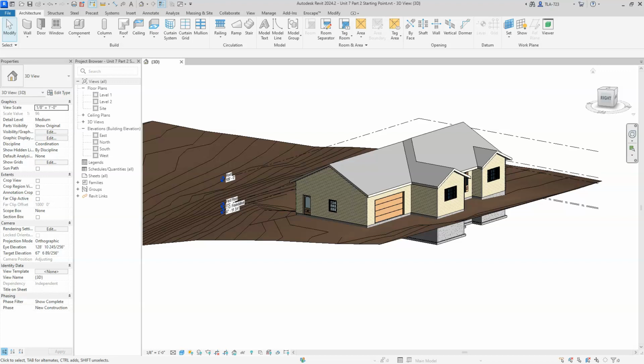We can pull in a background from one company, like the topo from the surveyor, and then we can either draw on top of that, or we can even link additional files into that same sort of common file in the middle. Linking projects together helps keep us from modifying or editing the stuff that doesn't belong to us, and that's really important as well. If we go in and we start changing the stuff that other consultants or other companies are providing to us, we can really get ourselves in trouble because things aren't where they're supposed to be. And there are all kinds of ways that we can adjust and change the view settings of those linked models without actually changing what those models look like or what their structure is.